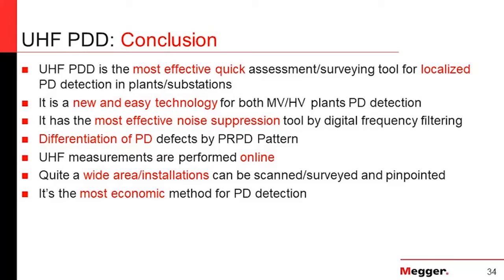And it's the most effective noise suppression tool. With UHF, we don't care about the noise because we don't work in the noisy area. And we can use PRPD with this instrument, which is very effective, and look into different partial discharge patterns and everything. And it's an online method, which is a big advantage.